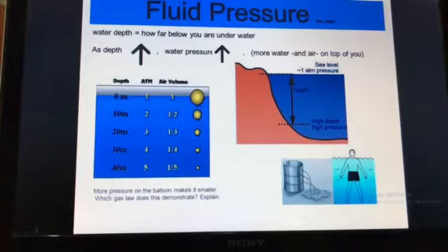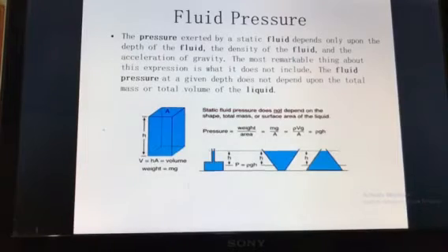We have derived that for a fluid whose density changes significantly with elevation, a relation for the variation of pressure with elevation can be obtained by dividing the equation by delta z. That means the pressure below is equal to the pressure above plus rho g into h. So this is the fluid pressure.